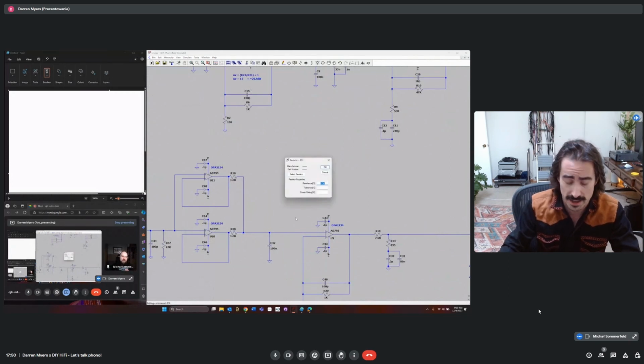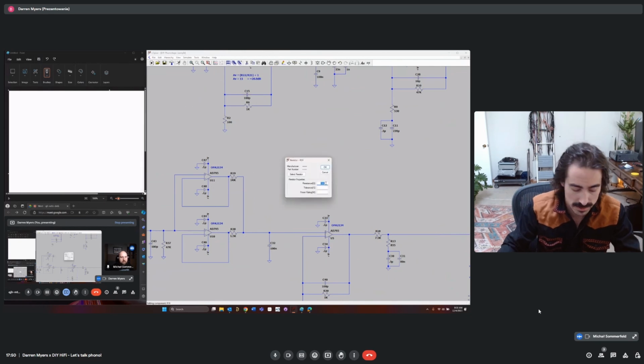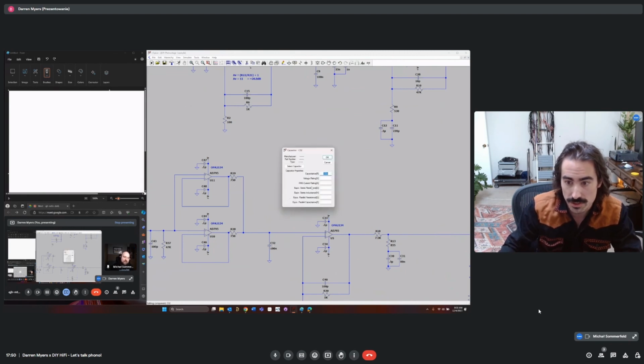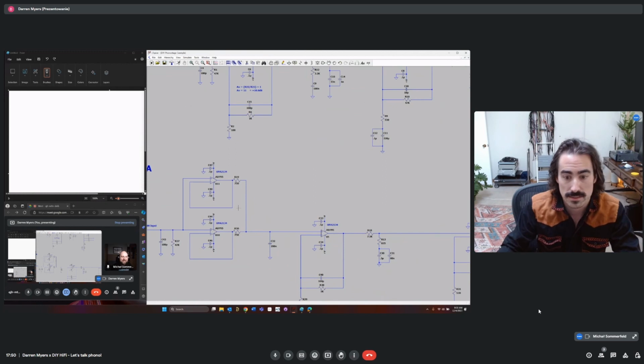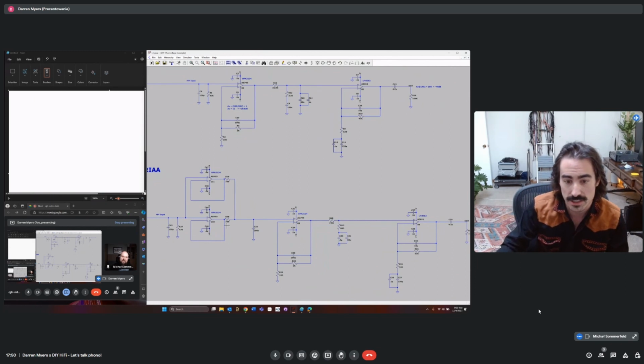Now you can see that we have room to move these down. Let's make each one 750. And then bump the 32. 750. Yeah. And then 200. And that's easy, because you could just parallel two 100 nanos. And boom, so now you have something. So that's a good solution to getting the best of both worlds.